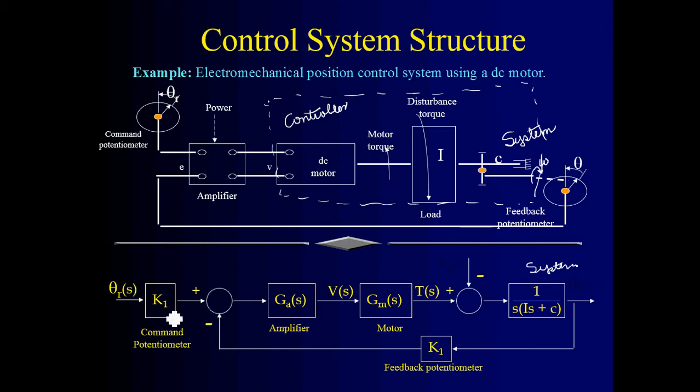This is the command potentiometer, meaning this is your dial setting, which transforms into a voltage, and this is of course right here your error in there, and then whether this gets amplified or conditioned, this signal goes to the motor. This is the command right here. This is the motor itself. This is basically your controller.